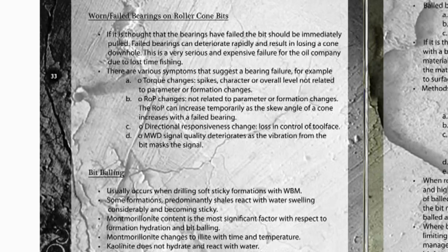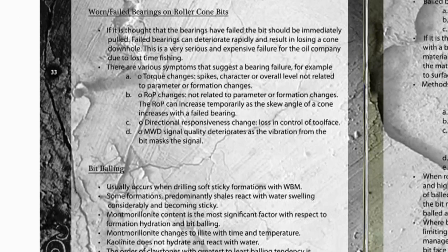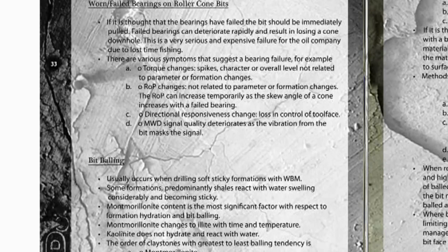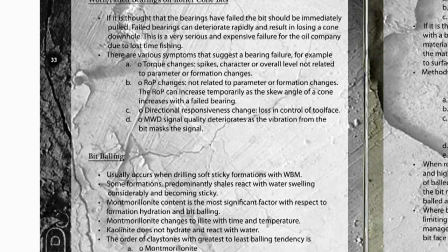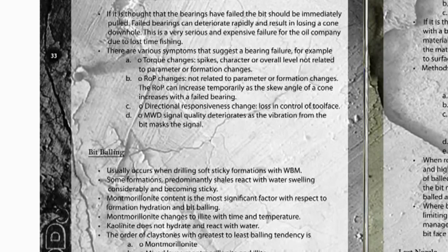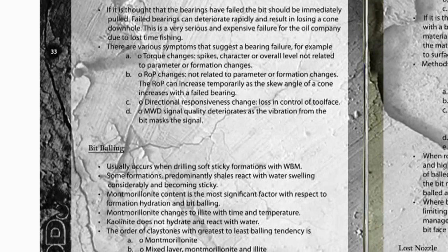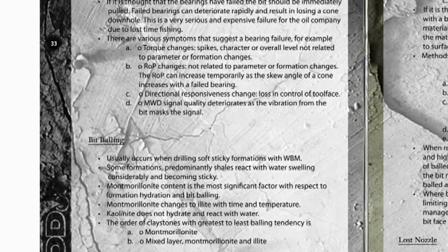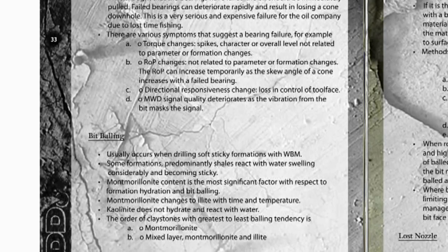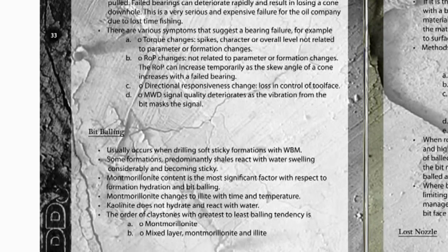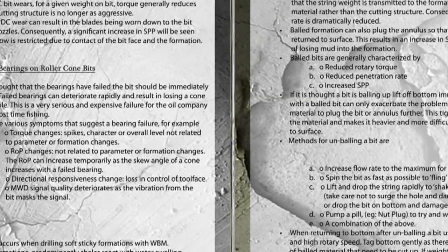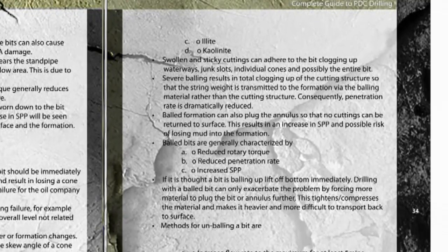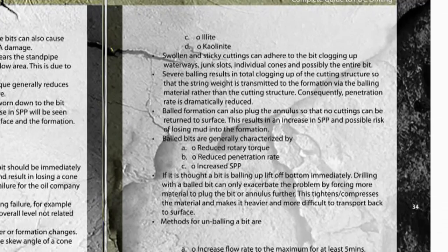Bit balling usually occurs when drilling soft sticky formations with WBM. Some formations, predominantly shales, react with water, swelling considerably and becoming sticky. Montmorillonite changes to illite with time and temperature. Kaolinite does not hydrate and react with water. The order of claystones from greatest to least balling tendency is montmorillonite, mixed layer montmorillonite and illite, illite, kaolinite.